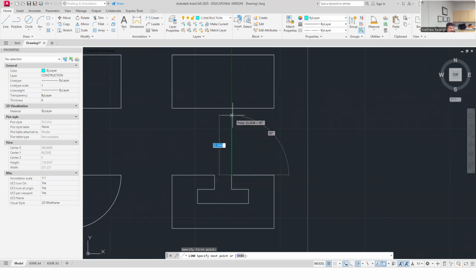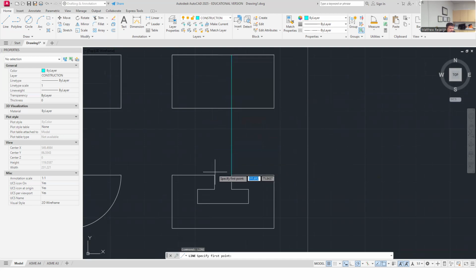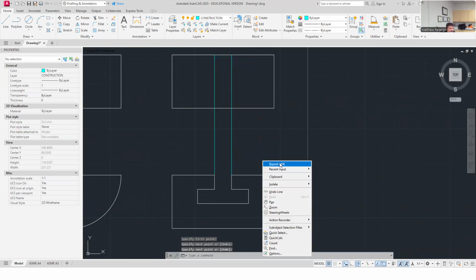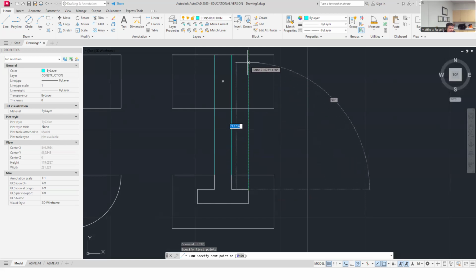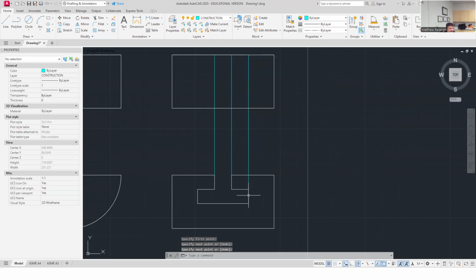This is going to be right where my eyeball sees on this upper surface of the top view. This one, enter, and then this is going to be hidden line work for sure. It's going to be the bottom of that. You know, this surface that appears as a line here is going to appear as a line here.